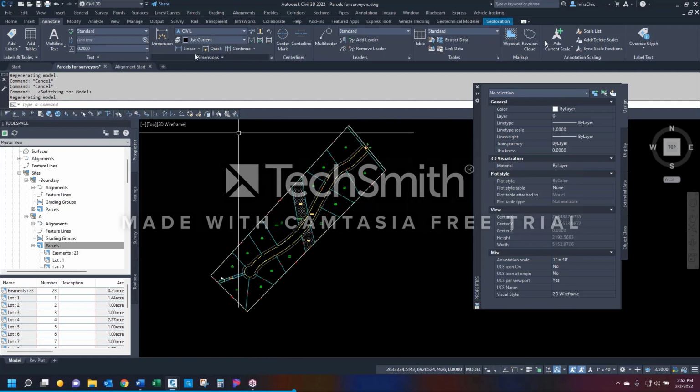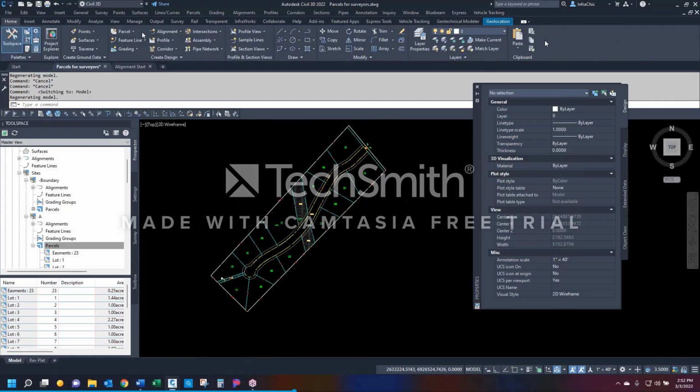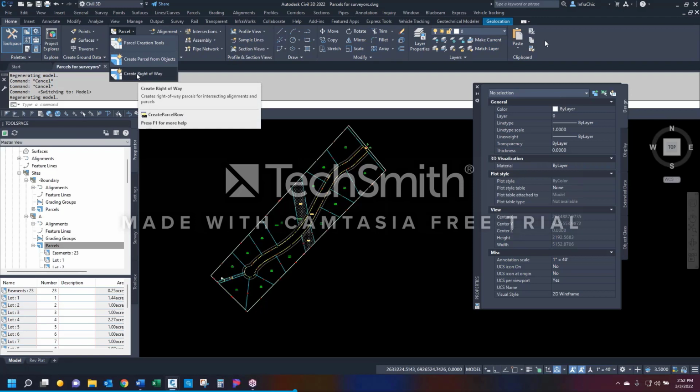All right, almost enough about parcels. So on parcels, I'm going to go back up to the home tab of the ribbon, create design. You can create a right-of-way. You have to have an alignment to do that. When you do create right-of-way, you select the alignment, you select the width of the alignment, and then how to handle the corners.